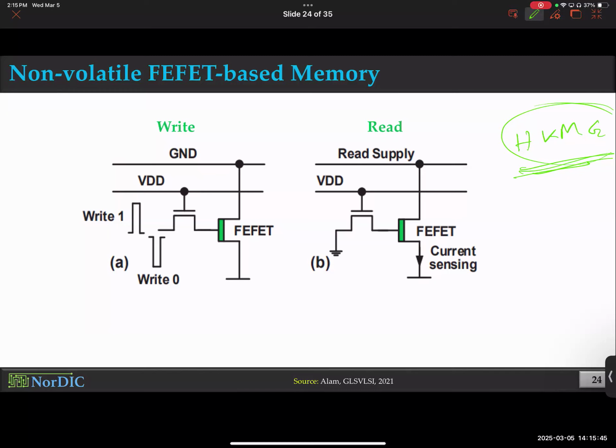All of these are linked together, but these are device level stuff. I'm not getting into this. But HKMG, what does high K represent? It's a dielectric constant. So there has to be a dielectric material. What is the dielectric constant for silicon oxide? It's 3.9. We use an oxide which has about 24, so 22 to 24, depending on how you make it. That's hafnium oxide.